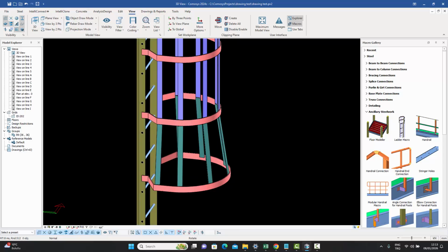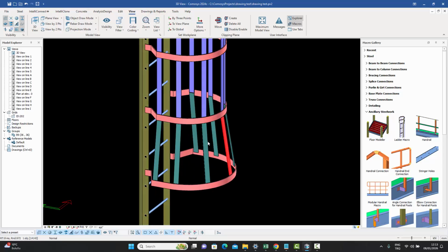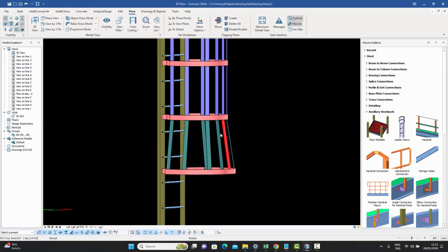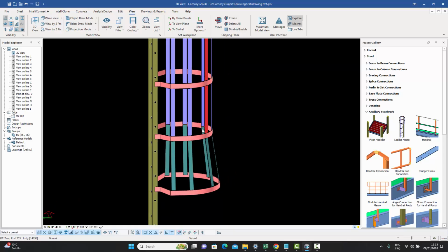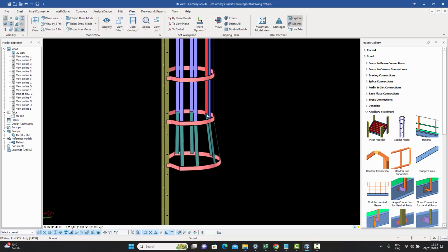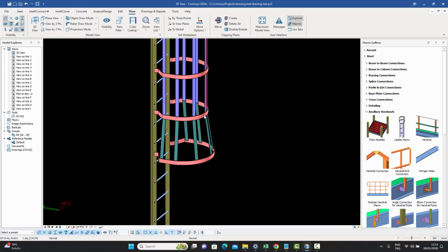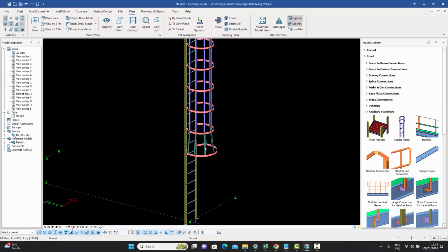So what this leads to is also a different style of these vertical plates. Previously these vertical plates would just come down straight, but now they have to be open, and you have the option to make it one continuous plate from here, which will be a folded plate like this, or break the vertical plates and then have a separate plate like that. Obviously, the input also changes.